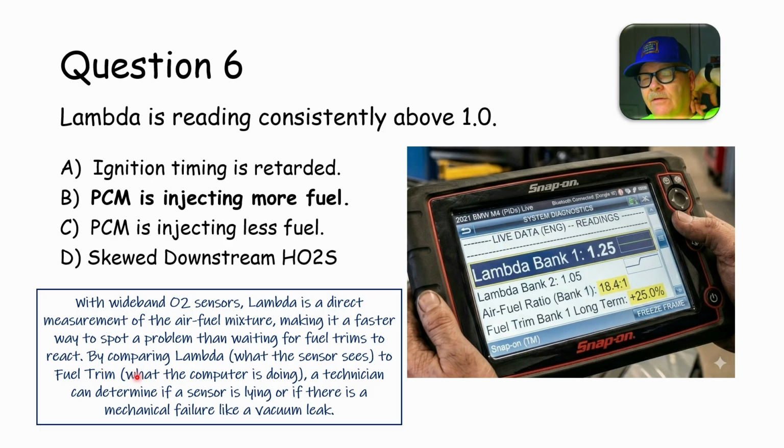Although, if you think you've got one fixed, like if you had fuel trims that were way off, like this one right here, your short fuel trim on this one here would be at 0 if the long fuel trim could tilt the mix enough. The long fuel trim is going to tilt off to one side to try to get the short fuel trim to stay at 0. And that's basically covering up for a problem.